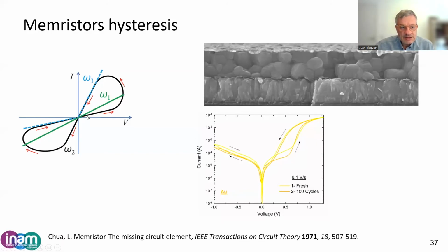The memristor is a state that, when you cycle the current voltage, has a big difference between a basic high resistance state and an activated low resistance state. So this is a switching device, and this is the basis for memory applications and also for making synapses in artificial neurons.